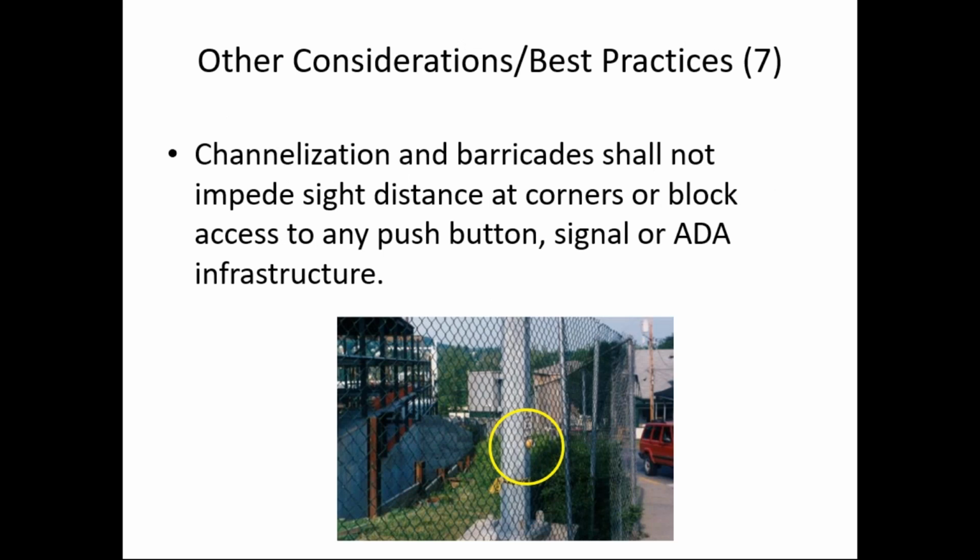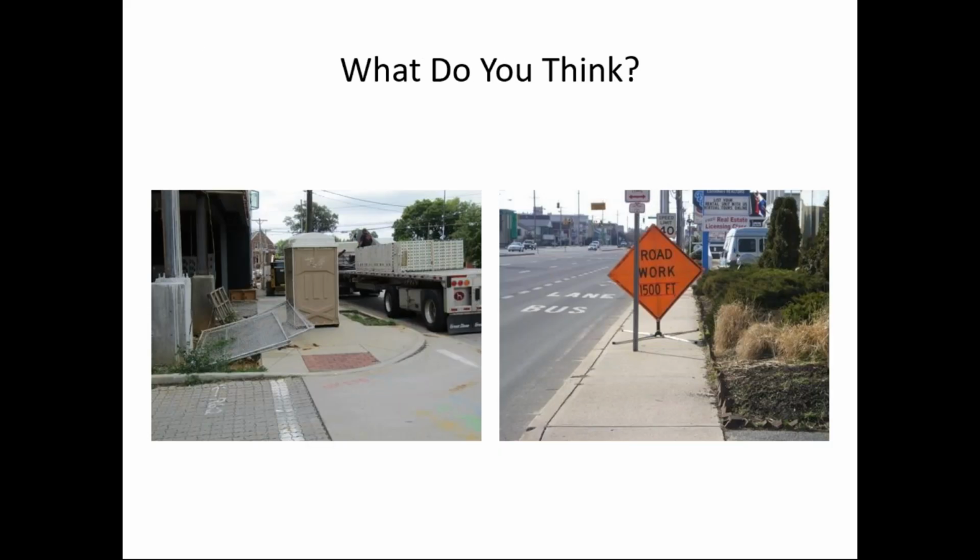This is sad too. Notice the construction fencing is outside of the pedestrian push button. So now the pedestrian push buttons, the signals, are basically inaccessible. Again, more examples of storage on the left there. In this case, there's a sidewalk only on this side of the street. And notice all kinds of stuff there: sections of fencing, the porta-john, it looks like maybe a skid steer or a lift in the background. So that sidewalk is inaccessible now, and there's no alternate route for pedestrians.